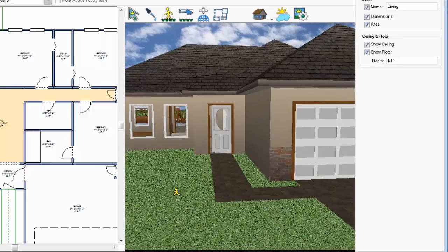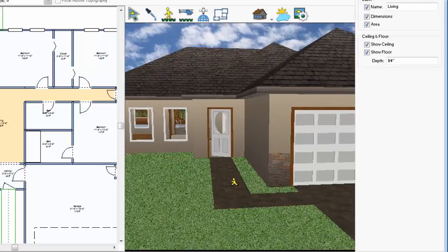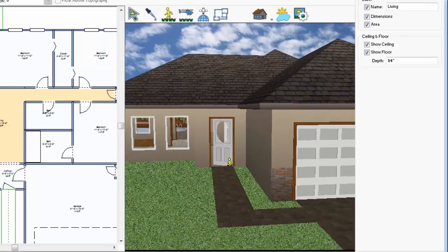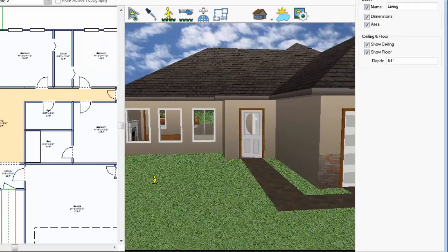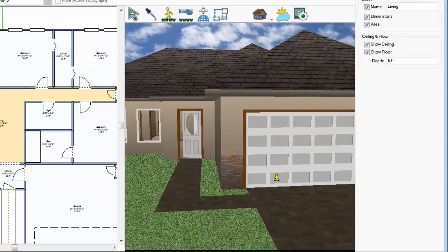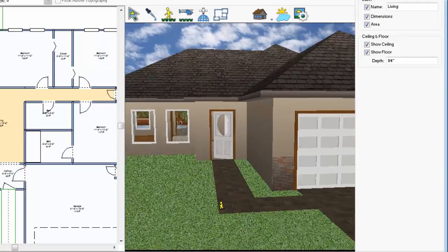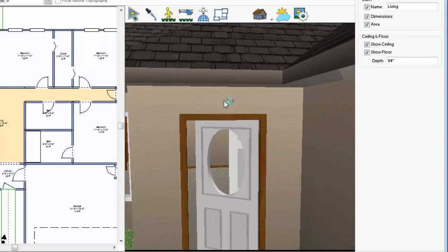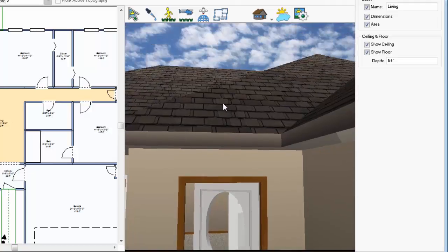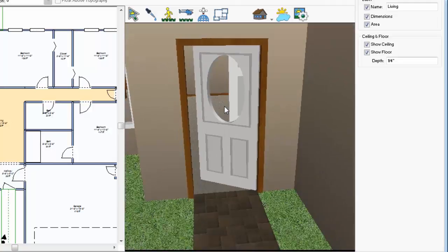Click the animated walkthrough tool, press the left mouse button, move it forward to move closer, back to move away. Press the right mouse button and do the same to move up and down, or pan left to right. As you move closer, you can use the wheel on your mouse and scroll it to stand there, but look up and down.